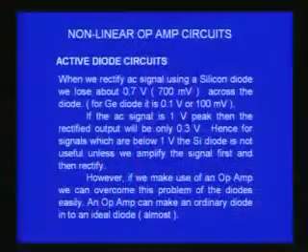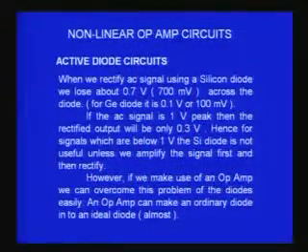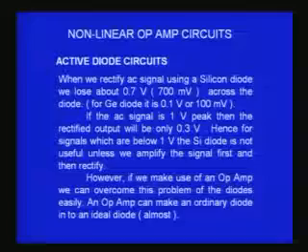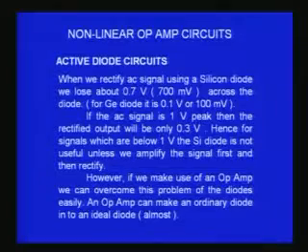Of course, there is one option available for you, and that is you can use a good AC amplifier. You can amplify the voltage to a larger value, so that 0.7 is very insignificant. When you amplify the 1 volt by 10 times, it becomes 10 volts. In 10 volts, 0.7 volts is not too much of a loss, and therefore you can calibrate using the normal DC. So, you must have an amplifier, but the amplifiers can be very expensive or difficult to construct.